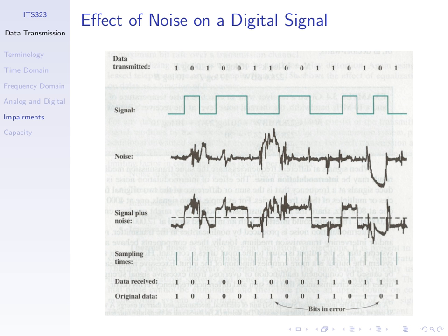Here we record the value, it's positive, therefore bit 0. Here we get a bit error, because what's received is different from what was transmitted. That's called a bit error. What was transmitted at this point in time was a bit 1, that is a low value. Sorry, it's this one. Bit 1, a negative signal, was transmitted, but there's a large spike of noise here. If we add this negative value to this large positive noise, the result is some positive value here.